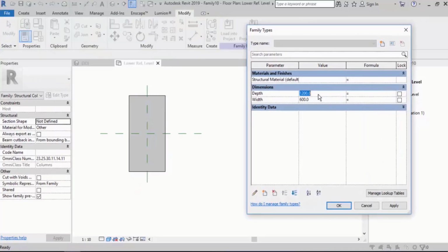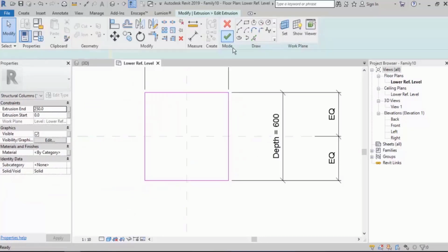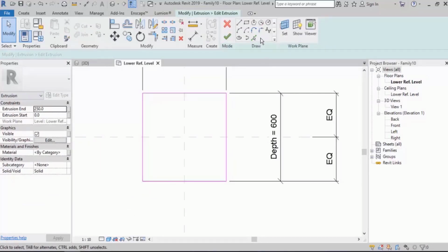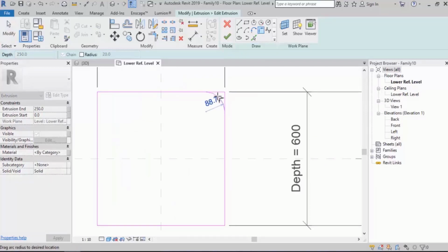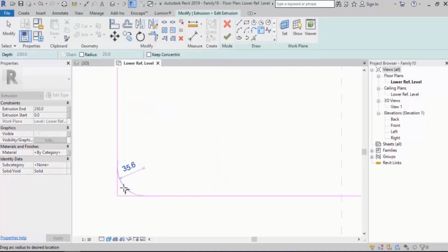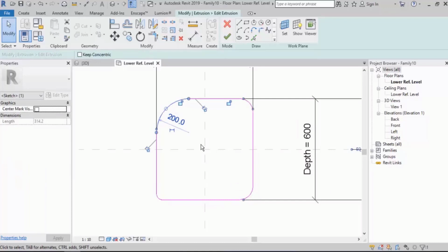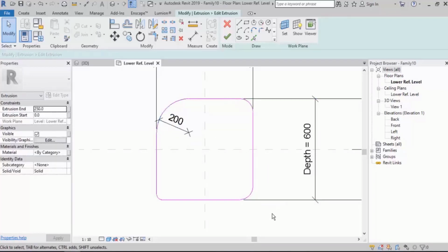Well, I said that we want to have a fillet, right? There's a small point too, I will tell you. Let's draw them not the same, right? All of them with different dimensions. None of them are the same. I'll select one of them. And for writing the radius, you don't need to actually go for the dimensions. Just select this. And this is like a temporary dimension, right? It becomes permanent when you click it.